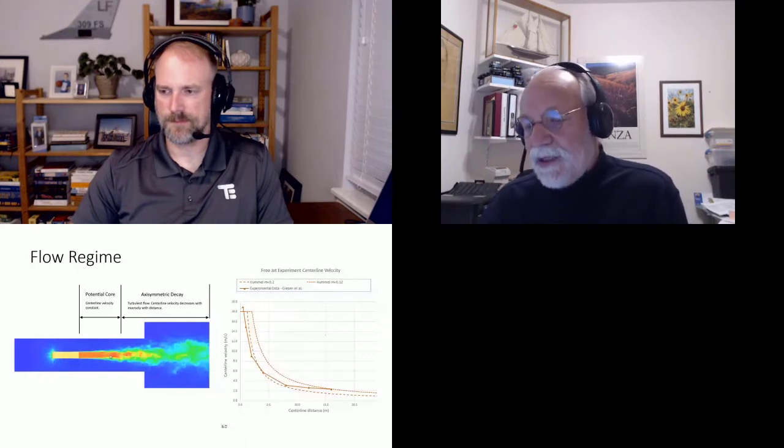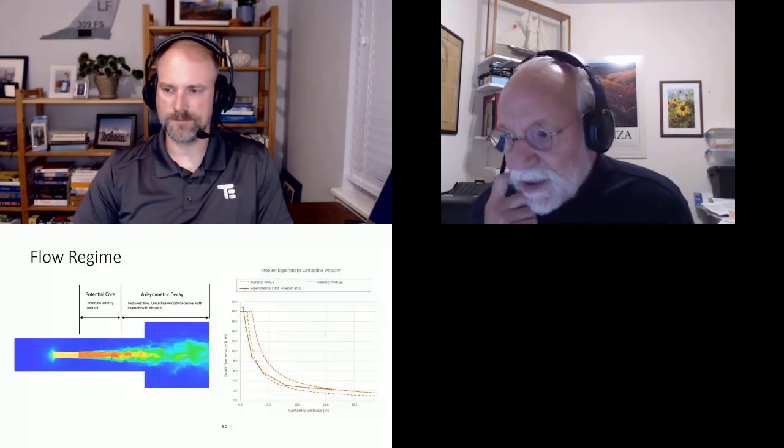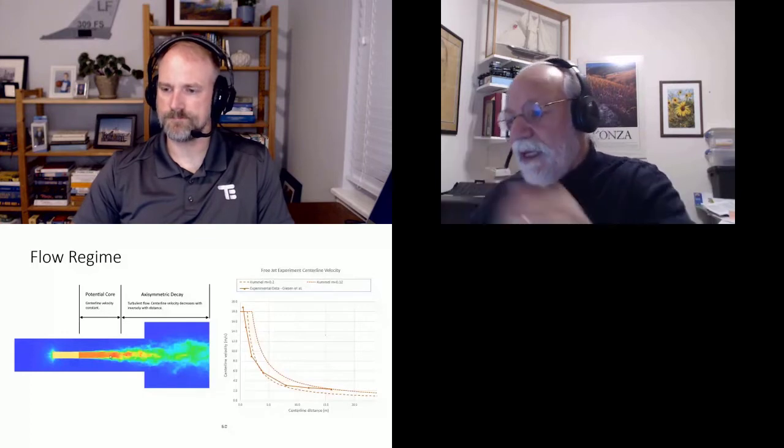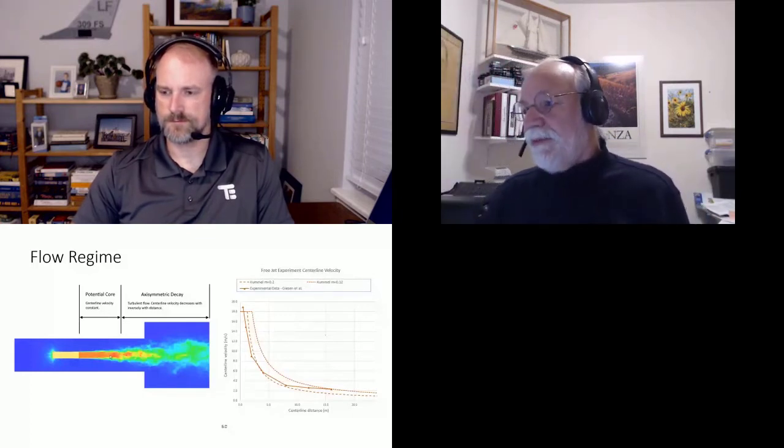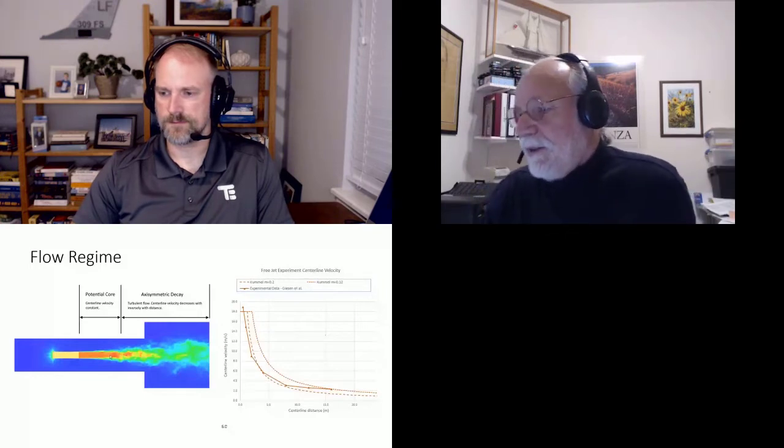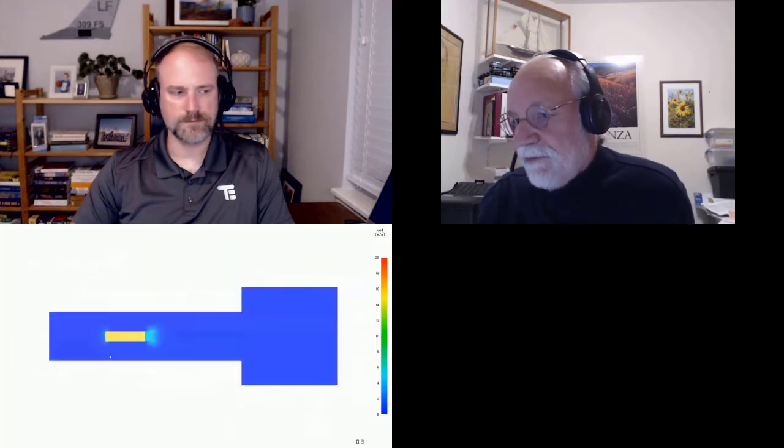The challenge is actually to model that transfer of momentum, because that is what then starts to move the air through the car park or through the room downstream. You can see that there's fairly good correlation between, on the right here, experimental data from Yuxin and some correlations that we expect to see from the jet flow.